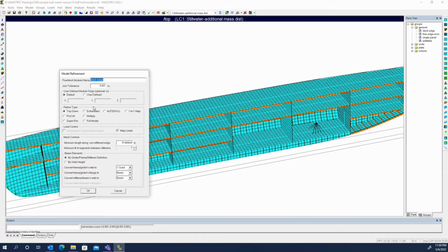This also, if you had used any of the pressure options on a plate, the appropriate portion of that load would get mapped to the fine mesh model, so that when it's run independent of the global model, those sort of loads that aren't on those boundary edges will be applied to the fine mesh model.